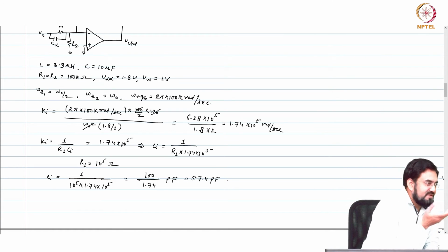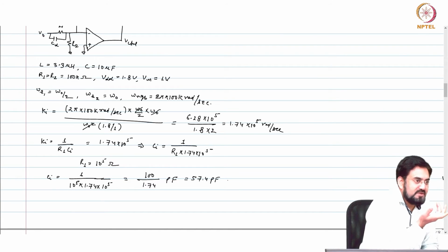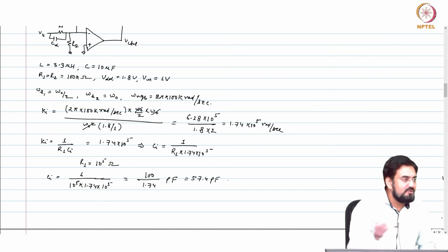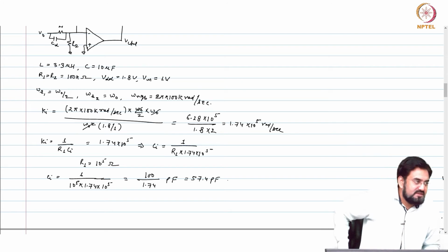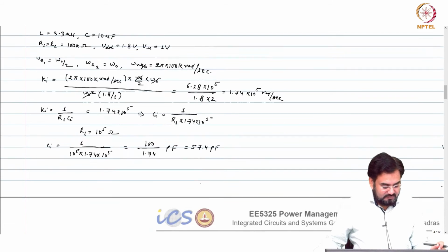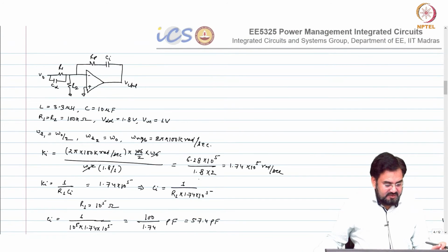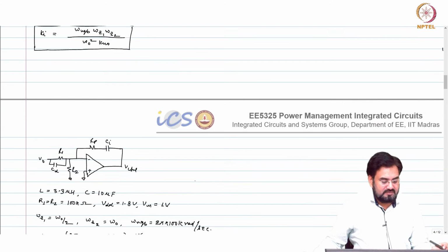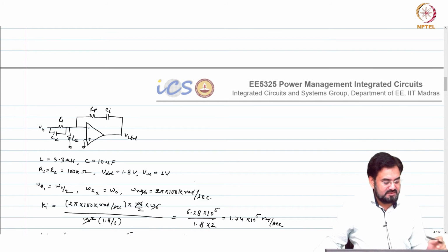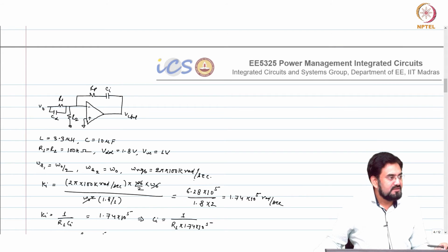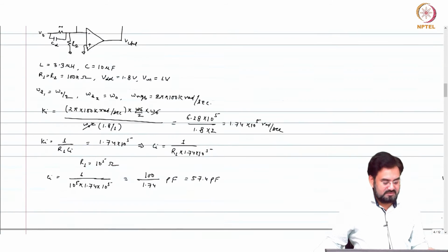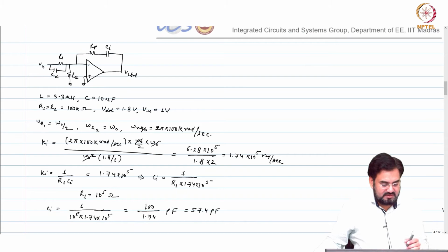Okay, which is same as what we calculated earlier, if you remember, because omega Z2 location we considered same. Now if you change omega Z1 or omega Z2, these values will change. So what else we need to calculate? We need to calculate Cd. What are the unknown components here? Rp and Cd. So Cd can be calculated, R1 is known. Okay, so that is straightforward.